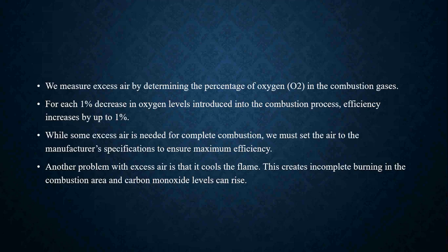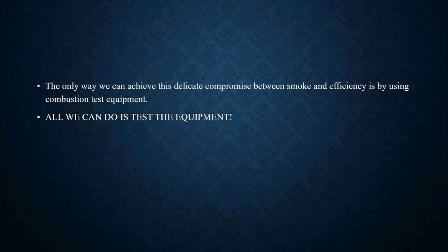Okay, another problem with excess air is that it cools the flame. This creates incomplete combustion in that combustion area, and you're going to have carbon monoxide. Carbon monoxide levels are going to go up. The only way we can achieve a compromise between smoke and carbon monoxide and efficiency and all that stuff is by using a combustion efficiency test.